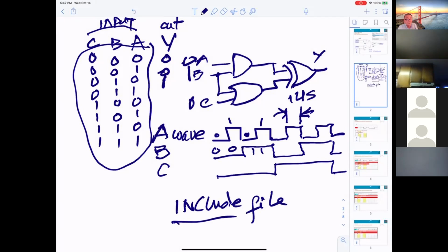This file helps you tell PSPICE this is the input of your circuit. The key point in here is the include file. The other things will be very easy. Draw the circuitry, run the simulation, not a big deal. But the include file is the file of your input applied to the circuitry. If you get the right input, then you are able to get the right output.